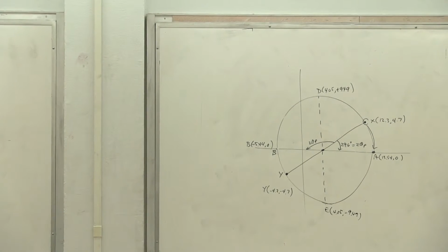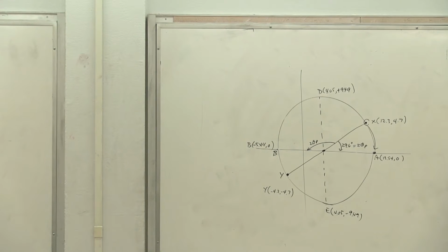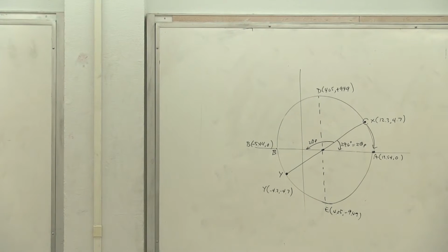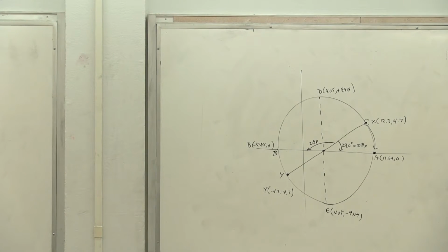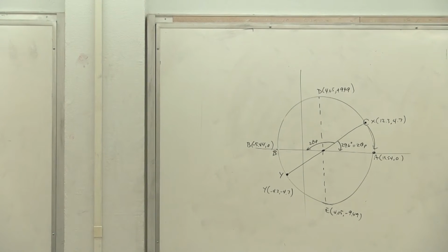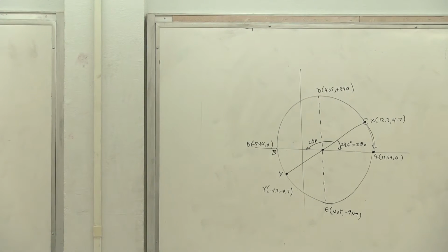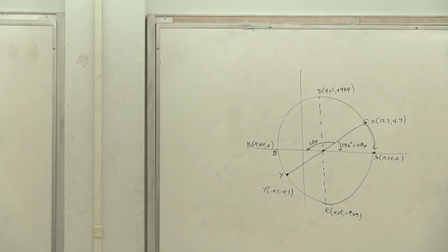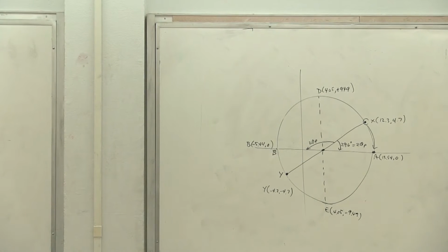Then there is a discussion here, which I'm going to do after we finish discussing. I'm a little bit behind there. So what we did, that is what? The first problem that you were facing in ME 218 was, okay, numerically, you can find all of it. Maximum shear, let me put that one down. The maximum shear is also equal to R for this problem. Is that correct or not? And R was how much? 9.49 KSI.